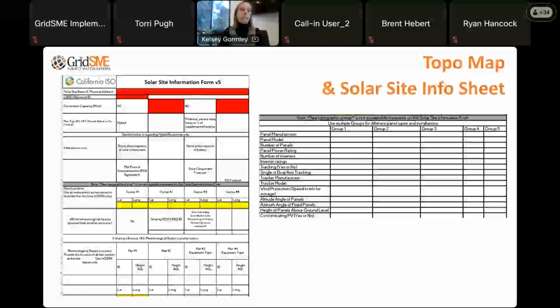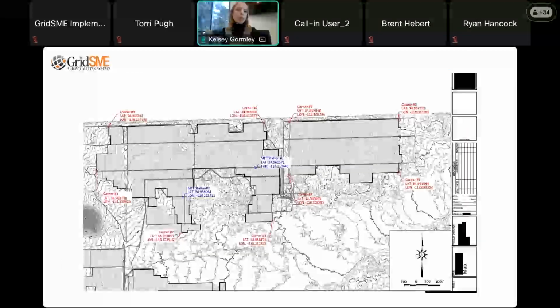And that corresponds with this submittal, which is a sample of what we would call a topographical map. I've seen a lot of gnarly things on topo maps, but what I'll just recommend highly to everybody is minimize the corners. I don't need to see 50 corners on a topo map. 4 is fine, 6 is fine. Anything over that is overkill. So please just minimize the amount of corners that you're identifying on the submittal, or ask your third party who's providing it to do so.